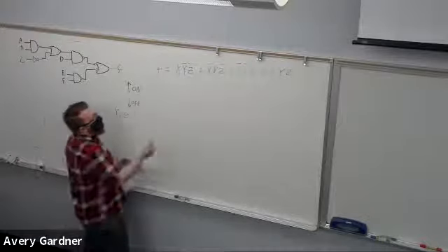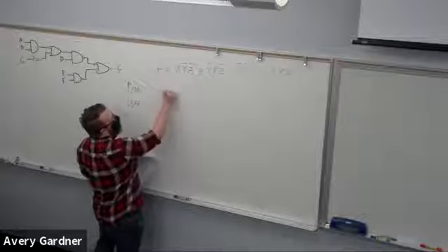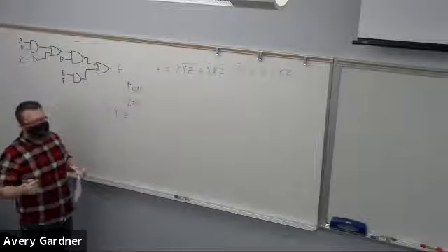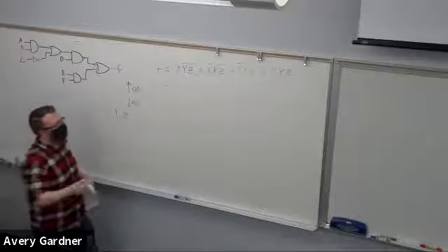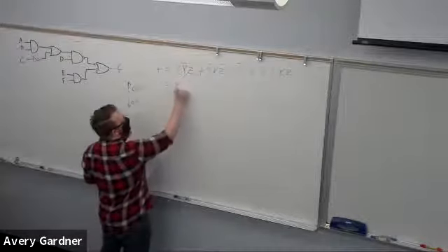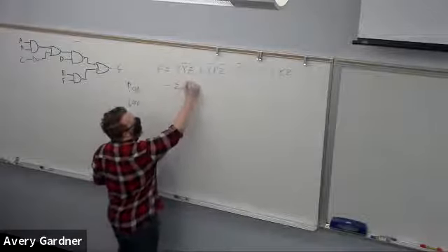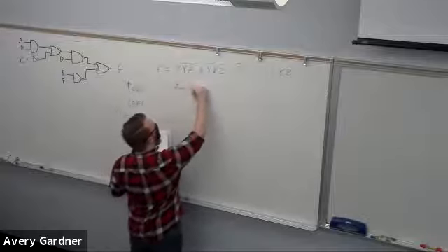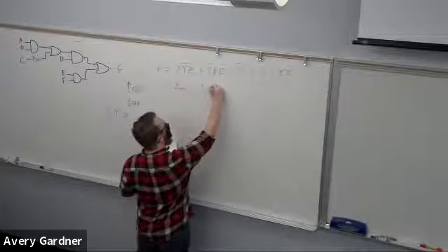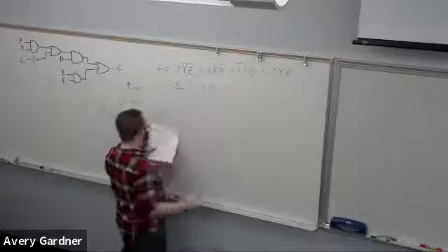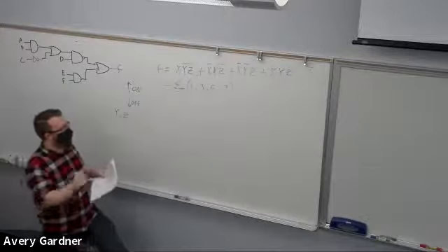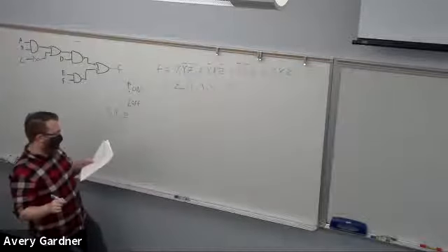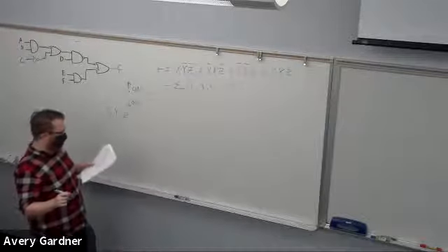Now, just recalling if this was an expression of minterms, remember how we did that? I could also say, and you may need to draw out this truth table to see this, but it's a sum of 1, 2, 4, and 7.